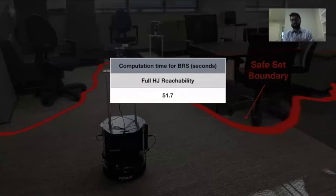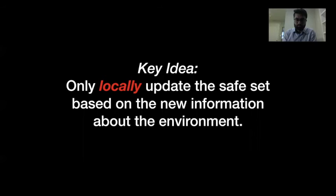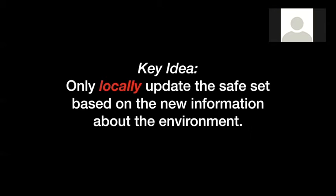The only challenge is that this is based on the principle of dynamic programming, so it suffers from the curse of dimensionality. For example, to compute this backward reachable set, we require 52 seconds, which is simply not possible for the real-time applications that we're interested in. To overcome this challenge, we only locally update the safe set rather than updating it everywhere. At any given time, we only receive very small new information about the environment, and hence we don't really need to update the safe set everywhere. We can update the safe set only in and around the region where we are getting the new information. That's the idea of the local update.